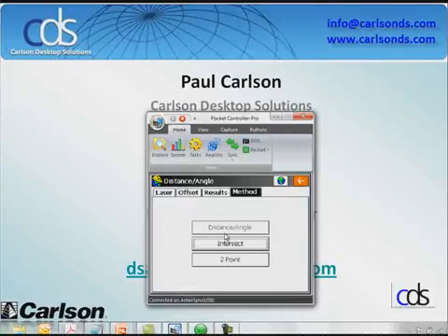You have other methods. You can do intersect. So I could go out and locate 2 points and say, intersect those based on the information that I've given you here. Do 2 points, and so on. When I'm doing the intersect, the elevation is interpolated based on where those 2 points would intersect. But again, it's all mathematics.